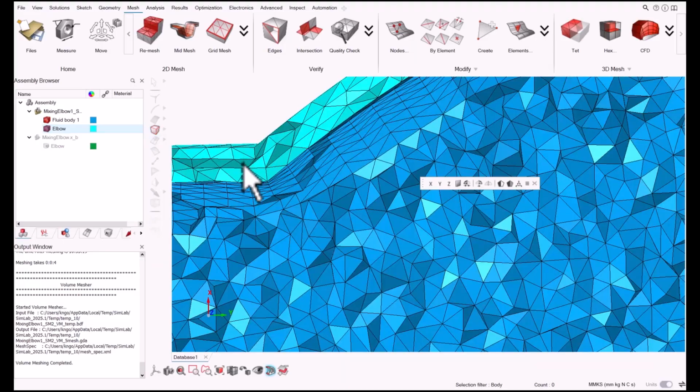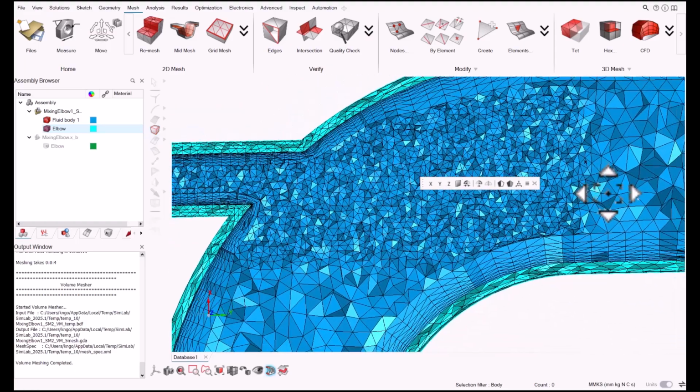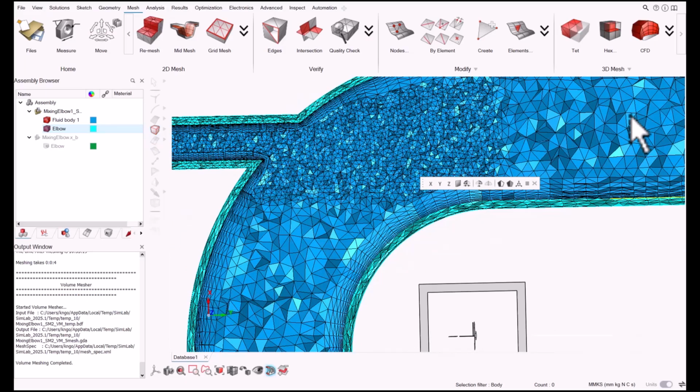Okay, we have three volume layers for the solids so that we can capture a conduction temperature profile. We see that the regional mesh control is being respected. We can clearly see the changes of the element size from the free elements to the refinement zone.